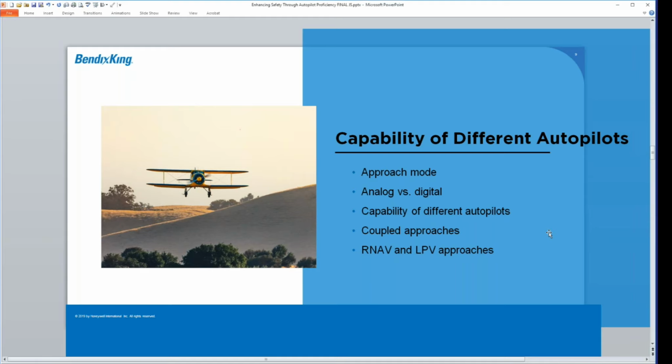So in this specific product, again, these autopilots really are designed digital. There's actually not even an analog to digital converter in this autopilot. It is just going to take pure digital signals. Number one, it lets us build a very cost-effective product. But number two, it lets us fly all the modern approaches. We do not do the analog approaches in it, but because it is a track-based autopilot, it actually provides some